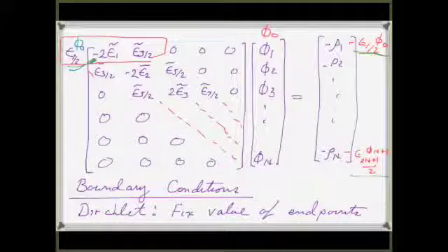And now what we're going to talk about is, so you've got these two equations now. You can think of it as Schrodinger's equation and your Poisson equation, where you're calculating the charge quantum mechanically, the electron density and hole density that goes into that rho. And then you're solving this to get the phi, and that goes back into your Hamiltonian to get a new rho.